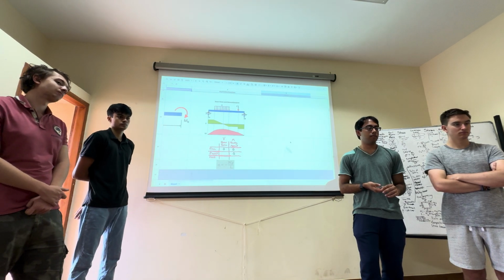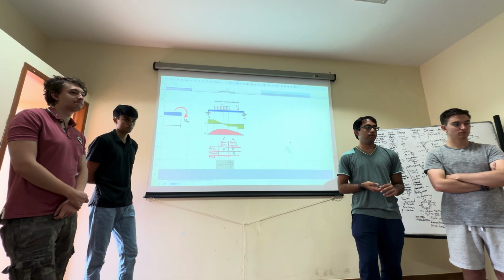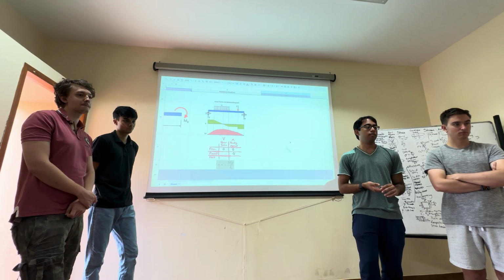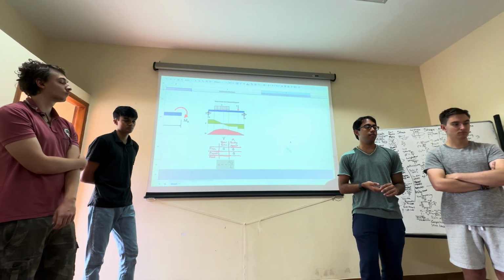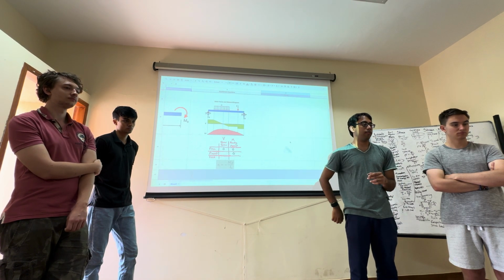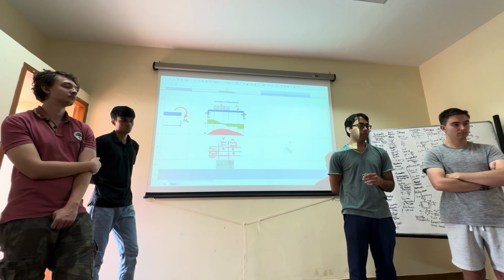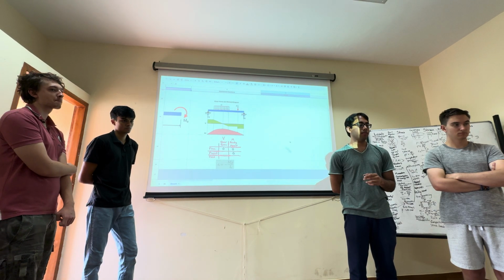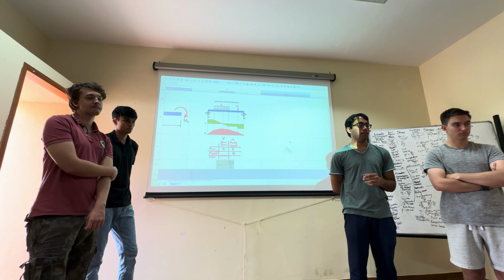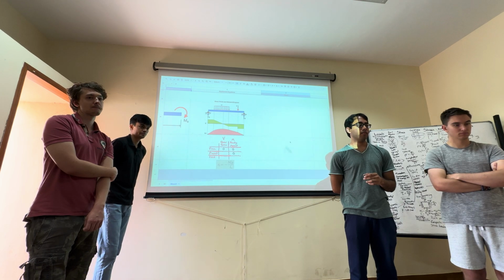It's saying displacement is 0, rotation is also 0, which is why when you draw the deformation of a cantilever, irrespective of how the load is, it will look very similar at the end which is fixed. It will always be 0 displacement, 0 slope. So that's how it will be. On the other hand, if you go to free, it's the other extreme where, because it's free, you do not know anything about either its displacement or its rotation. But you do know what is the load that you're applying. If you're not applying any load, you know that it is 0. If you're applying a load, you know what is the value of that load. It could be a force, it could be a moment, whatever. So that's the idea about it being free.